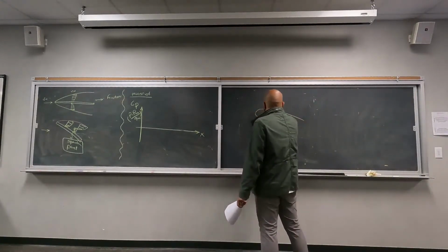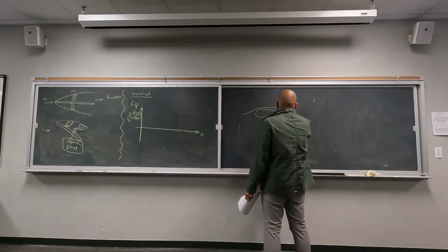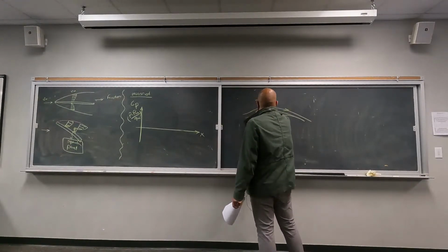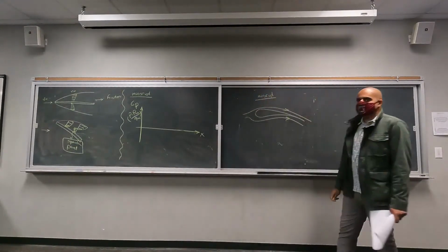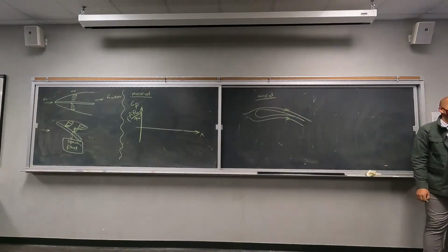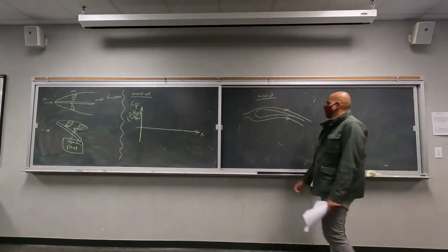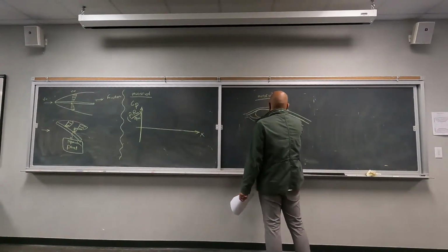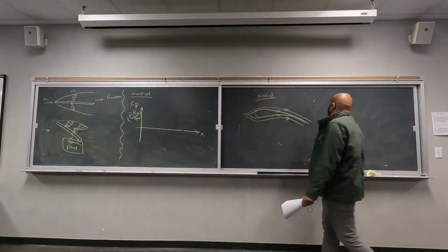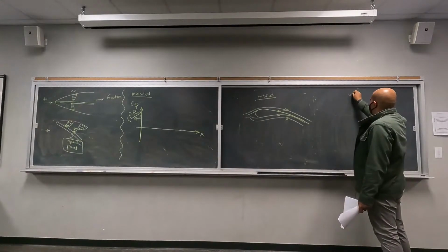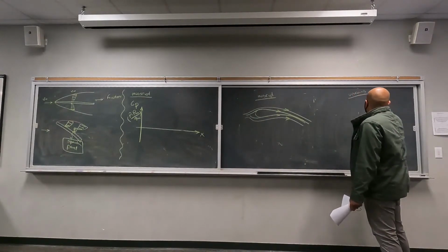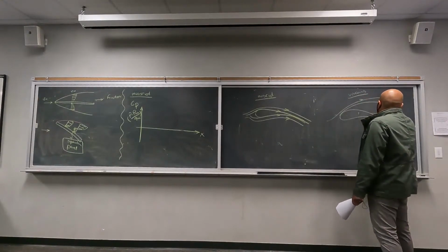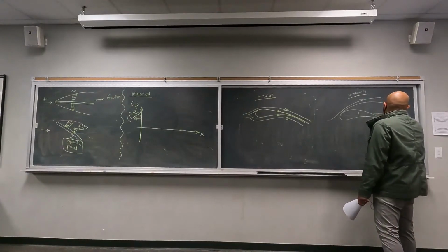The flow field is going to be different, which means that for the inviscid condition, your flow is always attached to the wall. There is no momentum loss. You're going to have the same magnitude of velocity everywhere on the walls, everywhere else as well, right? And for the viscous flow, in which we include the effects of shear stress, of course, we are going to have boundary layers, and you may have a region of separated flow.